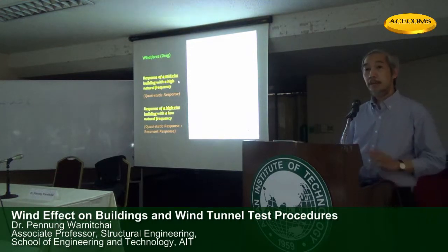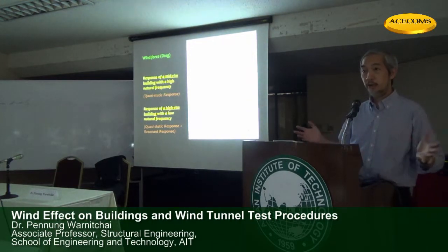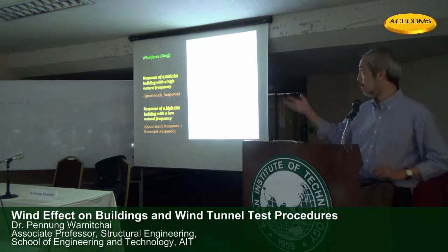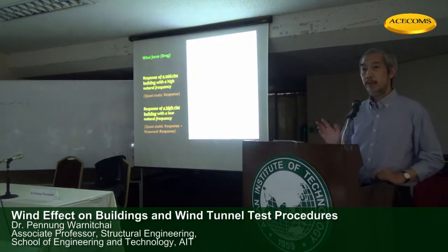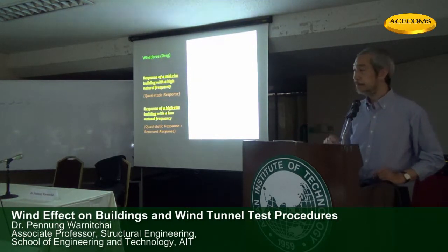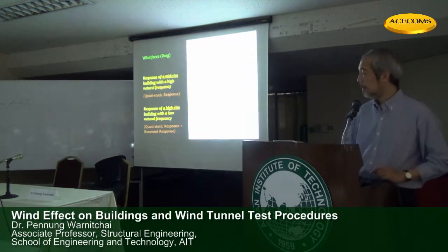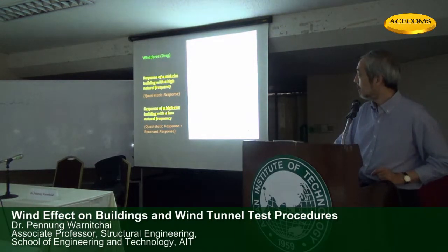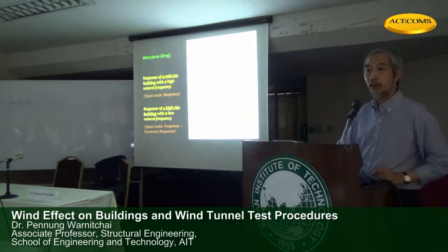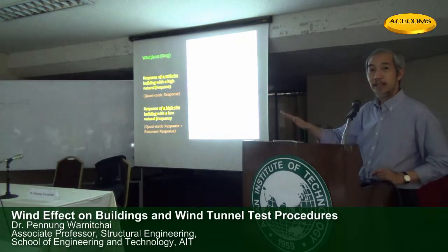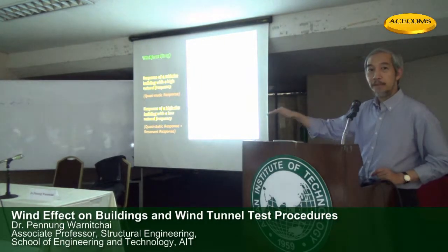Now, if the building is not so flexible, not so large, what we call a mid-rise building, with a rather high natural frequency, the response will be mostly quasi-static. It looks like static response. That means when the load is high, the response is high. When the load is low, the response is low. The response will increase or decrease in proportion to the load.